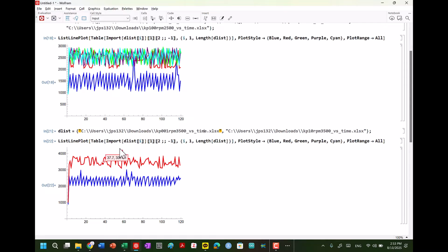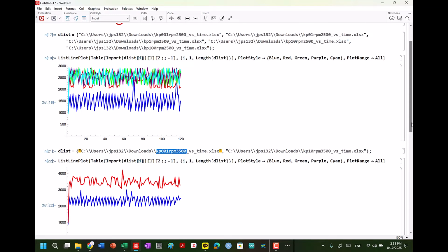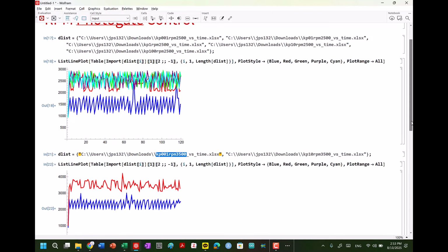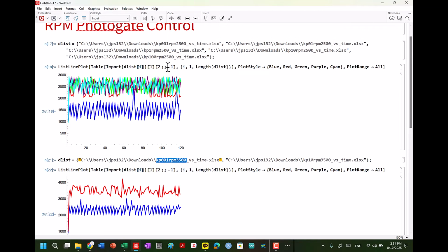And you can see here at this proportional control value, we can't even hit our baseline measurement. So we don't have enough proportional control to actually drive and hit our set point. And you can see these clear fluctuations where we're just not even hitting it. The error is constant. Here you can see improved control, and we're actually able to hit that at that 10 KP value. Now, as you increase that KP, you get a faster response, but you can get that overshoot, undershoot value as well.